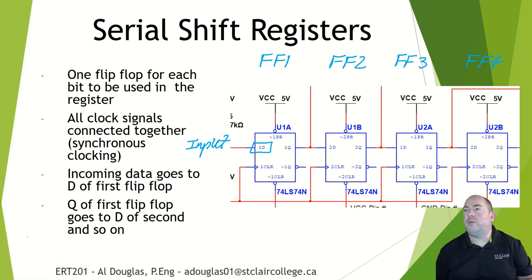You will also notice here we go from the Q of flip-flop 1, connect that one directly to the data entry of flip-flop 2. Q of here goes to the data entry of the next one. And we keep on repeating that process for as many flip-flops as we have.